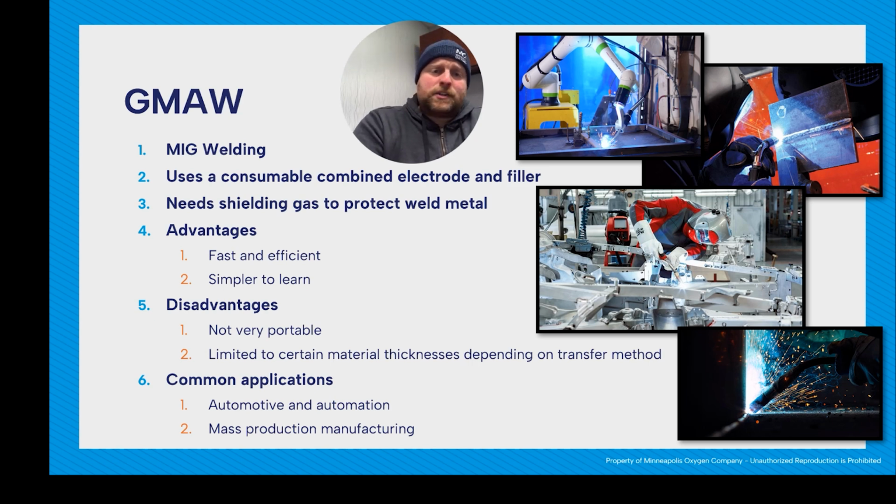Some disadvantages of GMAW is it's not very portable. You usually have a bigger machine, maybe an external or internal wire feeder, and your shielding gas, so it's harder to get around. And it can be limited to certain material thicknesses depending on transfer method. This is something I see all the time, where people are not using the optimal transfer method for the type of material and thickness they're welding.